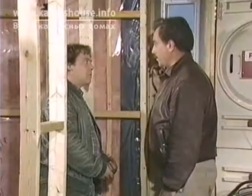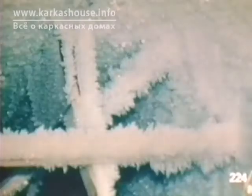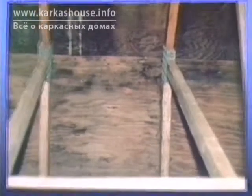I have to confess that's not my forte, moisture problems within wall assemblies. Where are the problem areas? Well, there are a number of them of which we have to be very careful, and I'd like to show them to you. Here are a few shots showing obvious problems. This is a frost boil formed around a plumbing vent in an attic. When that melts, you can just imagine what's going to go on down below. This picture shows excessive frosting on roof boards in an attic. And this one shows exterior sheathing, badly deteriorated because of excessive moisture.